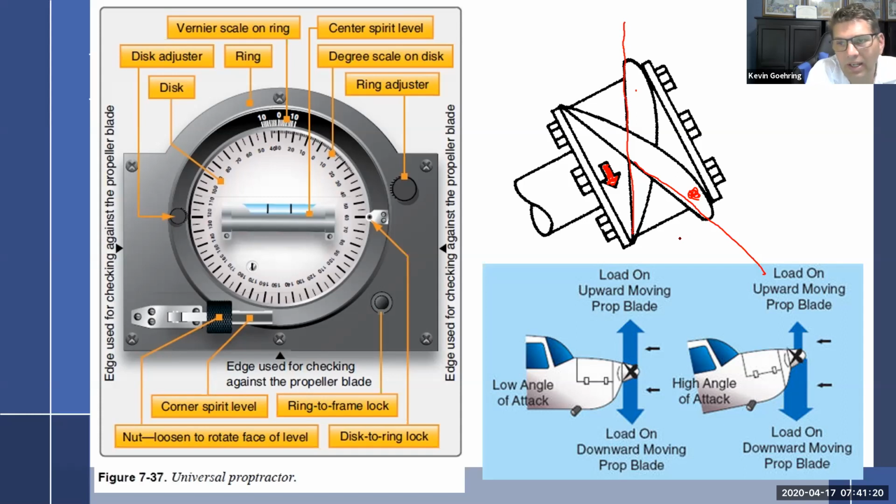And that's different than gyroscopic precession on a prop, which is if you have a tail-wheeled airplane, when you lift the tail wheel up, the airplane wants to go left because of the gyroscopic movement, which is something different. This is P factor. I'm not sure what the P stands for. I think at one point I knew, but it doesn't stand for pucker. I know that much. I think it's propeller factor actually. And so anyway, that's P factor. So it's an asymmetrical loading on the propeller.